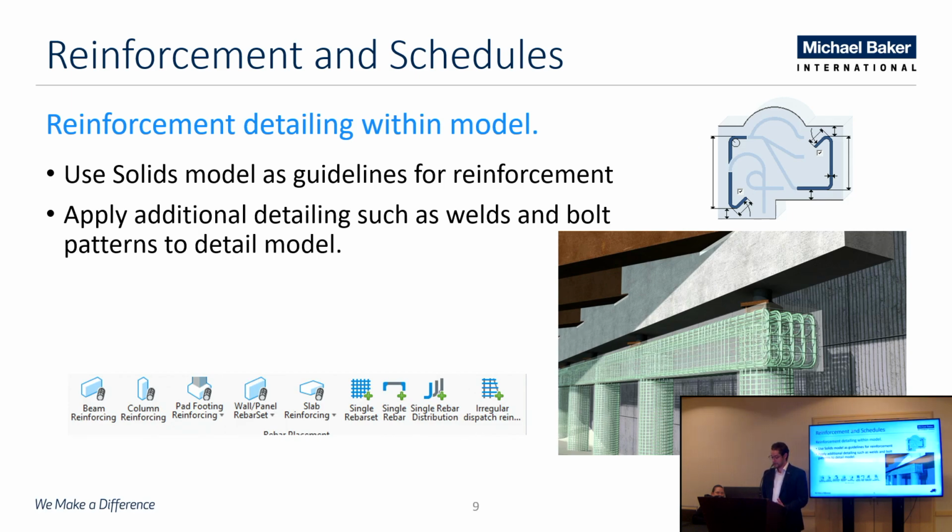That's not to say that you don't have to modify it after that a little bit. There's always going to be crazy elements like your diaphragms, a little bit more complex elements that you're going to have to go in and create that different reinforcement for. And that's really what takes the time with detailing, is those little bit more complex elements. Those simplified elements, though, if that 3D model changes, that reinforcement is tied to that 3D model. So that reinforcement can adjust based on those parameters that you've initially defined for, say, that slab or that column, whatever element you have there.